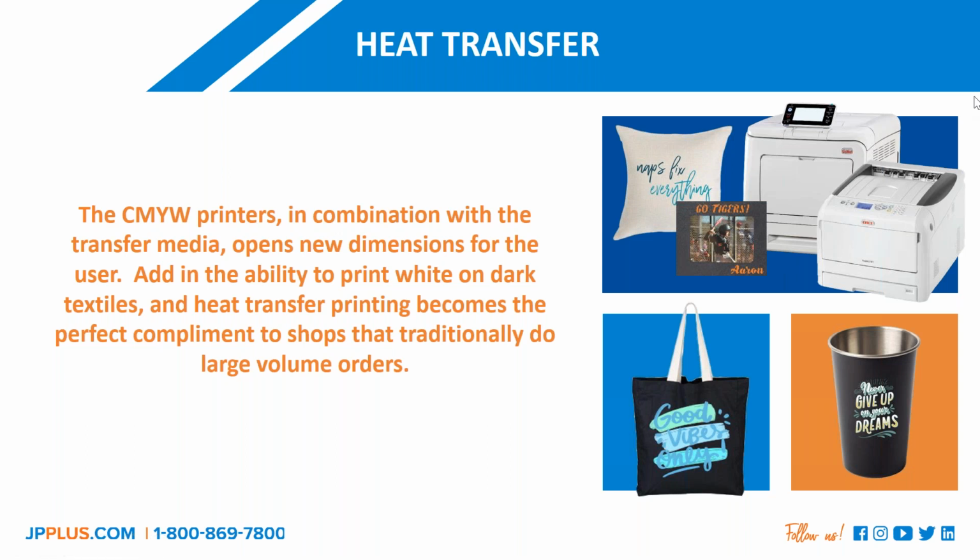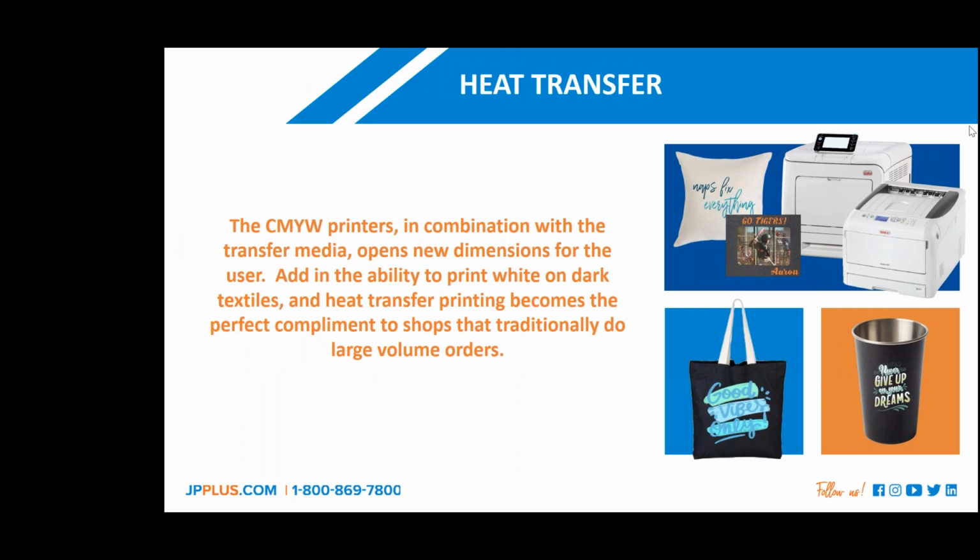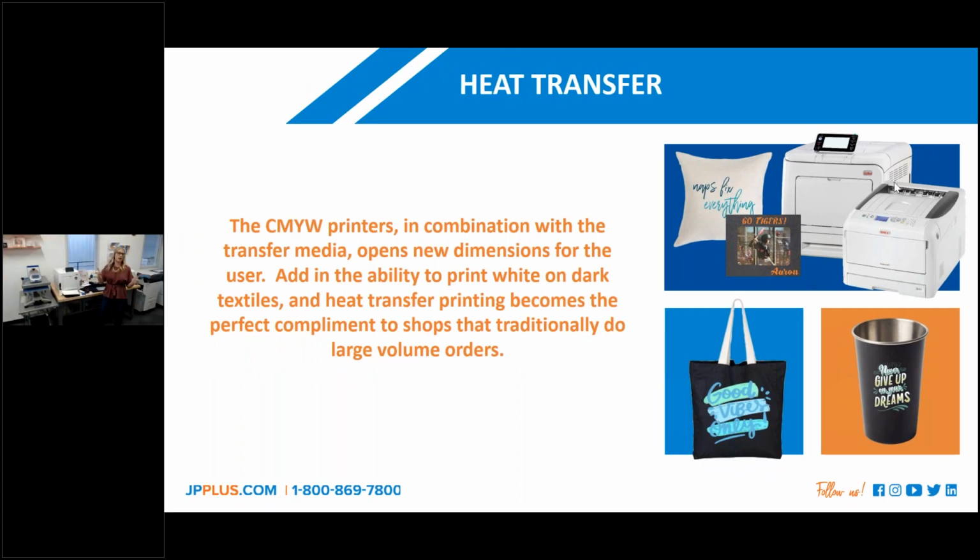Yeah, so with sublimation, I like to steer away from the clamshell presses. And I'm going to turn my camera back on here so you can see me again. All right, can you see me okay? Good. So clamshell presses are going to come down back first. With sublimation, it is extremely important to have that consistent pressure going throughout.